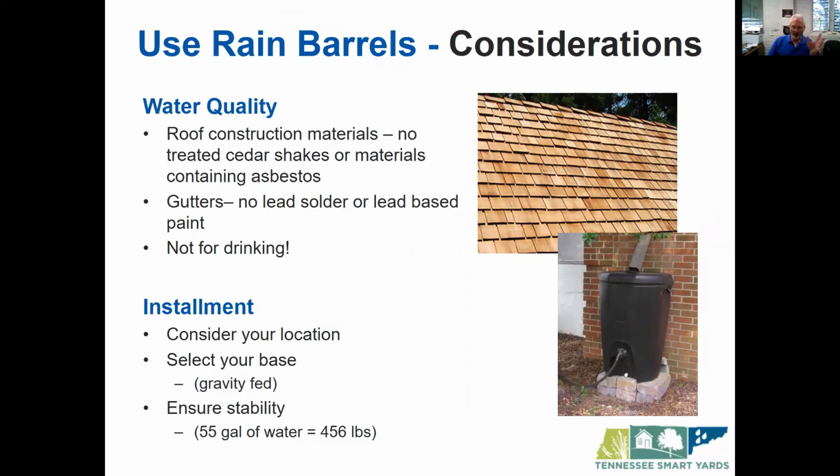But it's important to remember we are not creating drinking water. We already have potable water available to us. There is going to be bacteria in the rain barrel. Not necessarily bad bacteria, but there's going to be bacteria there. Birds do what birds do, and that will be flushed off the roof with the rain event. Now, if bacteria is going to concern you, there is a simple solution. A cap full of bleach in a 55-gallon drum will eliminate the pathogen load.